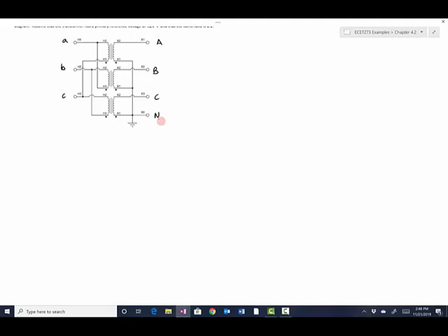So what I want to do next is identify each of the individual transformer nodal connections, and I'm going to assign each terminal a 1 or a 2. For example, a1 or a2 or b1 or b2, etc. Ones are going to be assigned to the terminals connected directly to the letter, and twos are assigned to the opposite terminal of the same coil winding. So I am going to come here and see, for example, this is a right here, and I am going to say, okay, that is a1. It's connected directly to a, and I'm going to call that a2 right there.